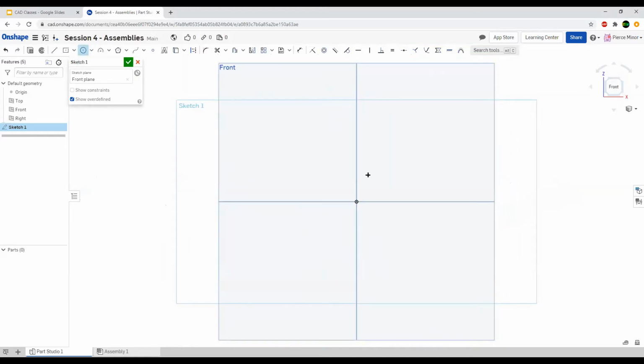So we want to have our output shaft. Let's put it out there for now. This is going to be a bearing that is 1 1/8 inches in diameter, so I'll just put 9/8 here. And then next, let's put the 52 tooth, I think I said, gear that we are going to have on here.